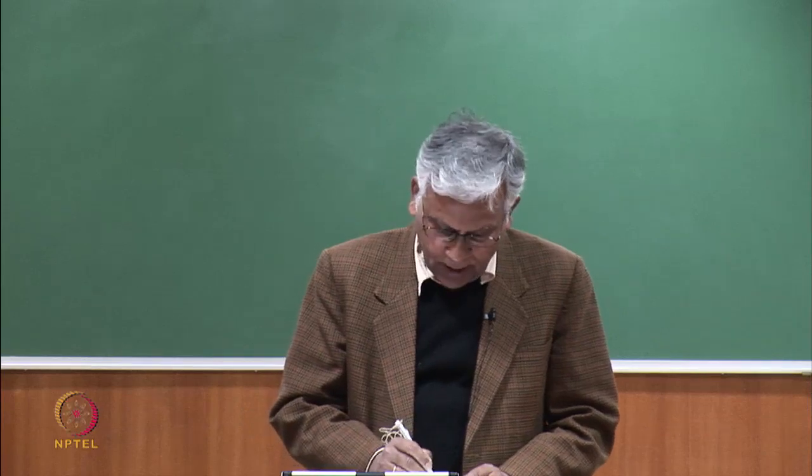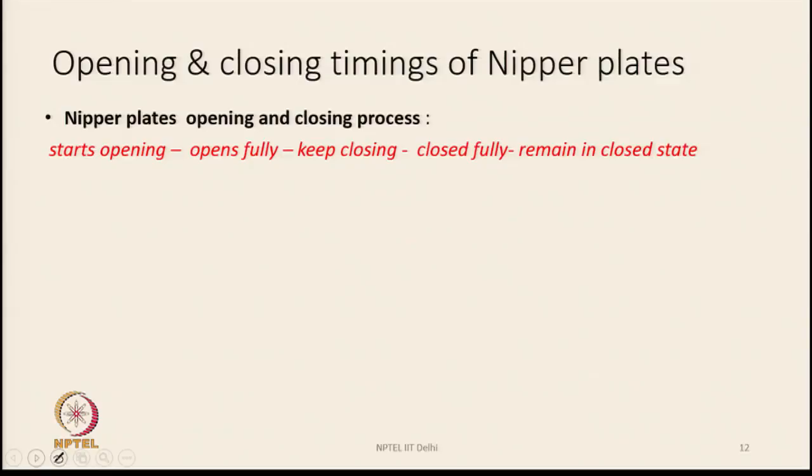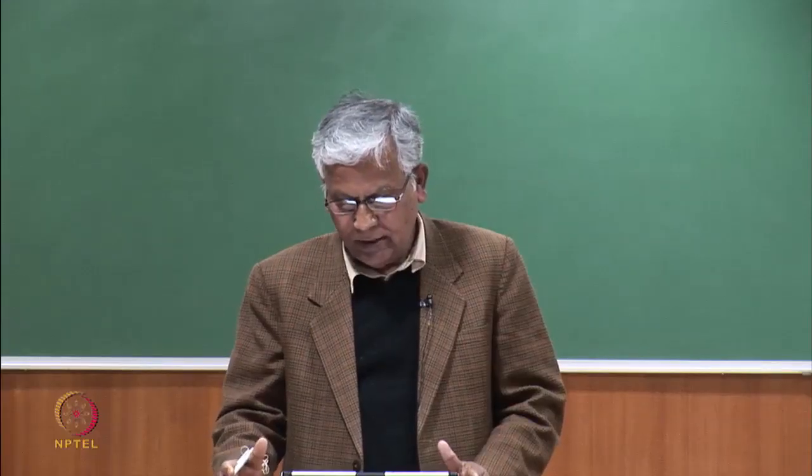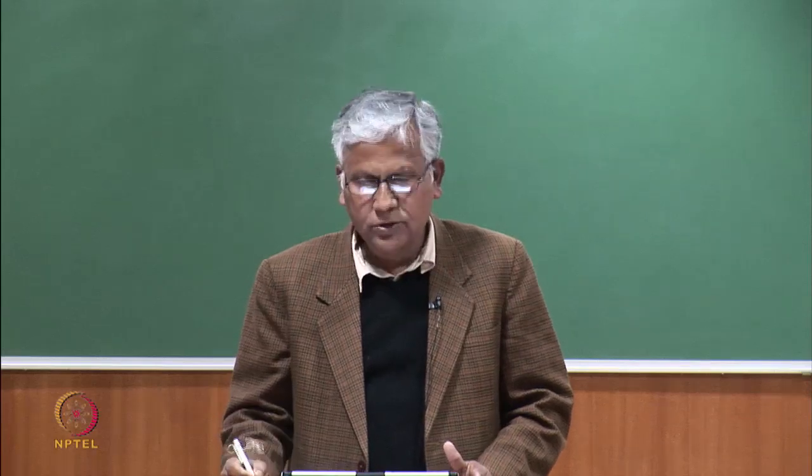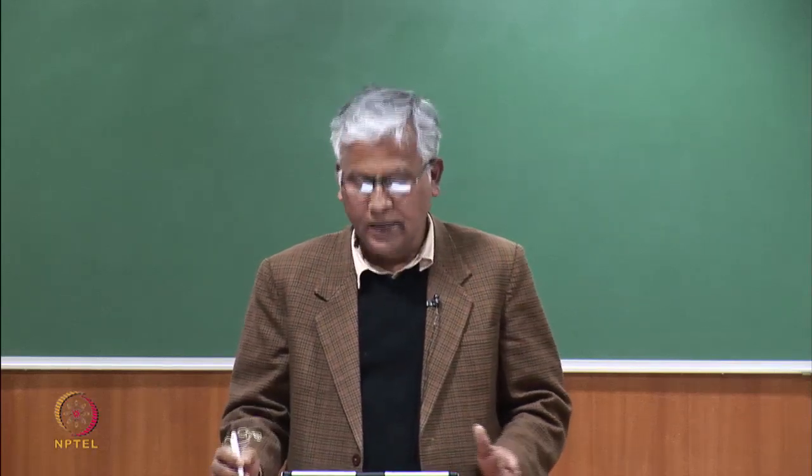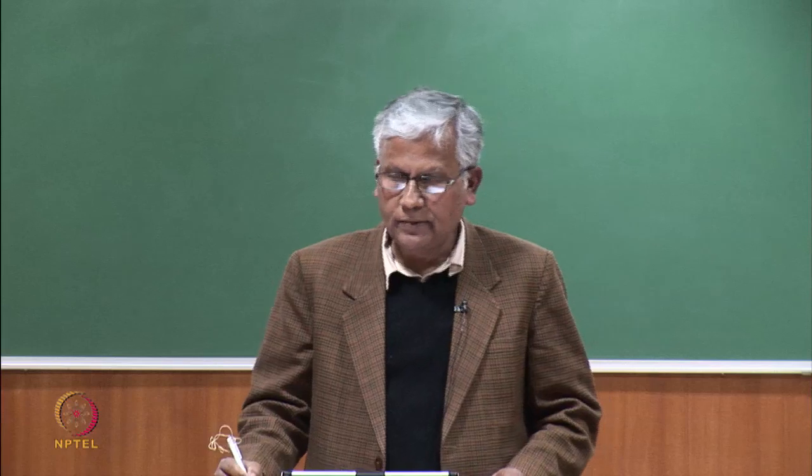So, we have to open and close them in order to grip the lap that we feed. So, nipper plates opening and closing process, it starts opening, then it opens fully, it keeps closing, closed fully, and then it remains in closed state for some time. In any given cycle, this is what is going to happen.